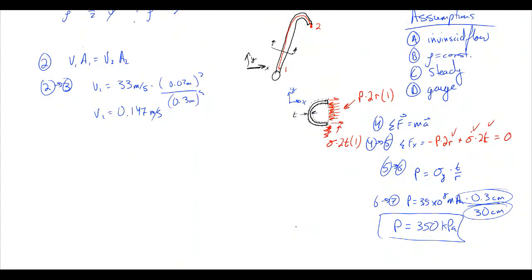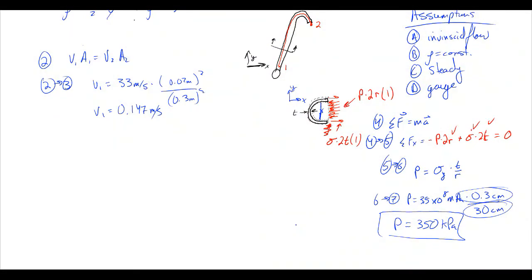Increasing the thickness increases the weight of the tower, and decreasing the diameter of the tube increases the viscous losses within the tube, right? Because remember, viscous losses always scale with the velocity over the length perpendicular to that velocity. So we have fluid coming up. Let's draw a little arrow coming up through this tube. So the distance perpendicular to that velocity, this distance, as it gets smaller, our viscous forces get larger and our viscous losses get larger.